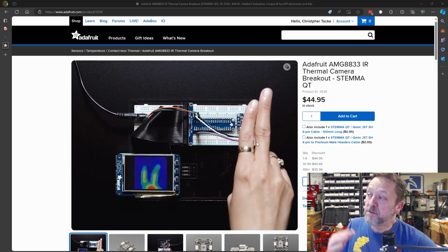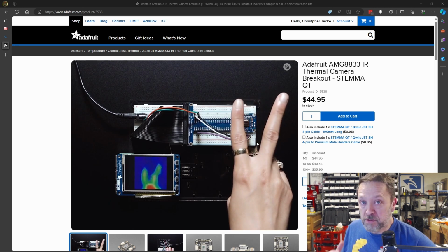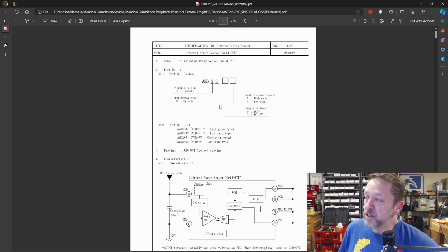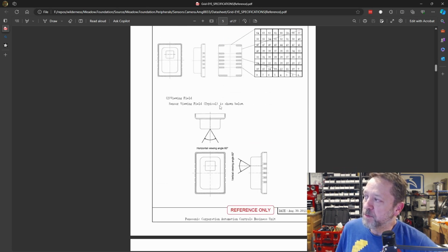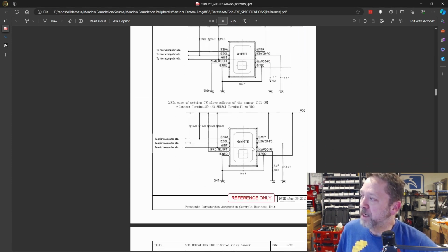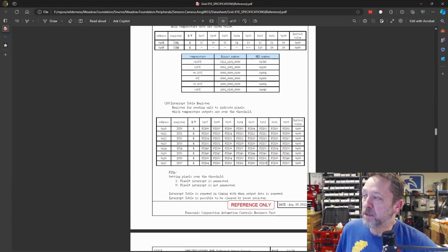I did do it for this project, and it took me about half a day, I think, about 4 hours of development from the datasheet. This is the datasheet here. Very typical datasheet. It's got some electrical specs, but you can see here that it has 64 pixels, and you get back a temperature by reading somewhere down in here. There is a register, there we go, a register of the pixel temperatures, and it gets back data in degrees Celsius with quarter-degree resolution.